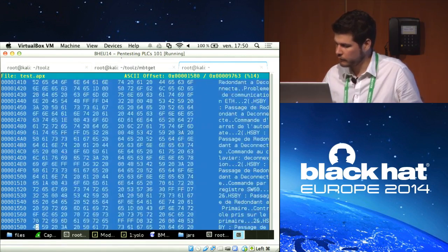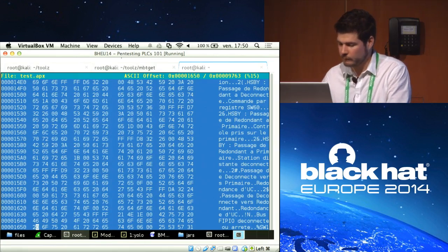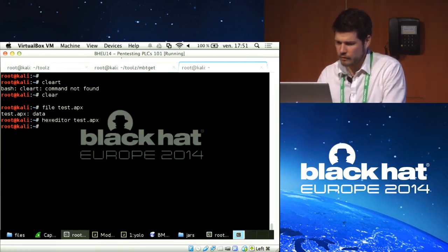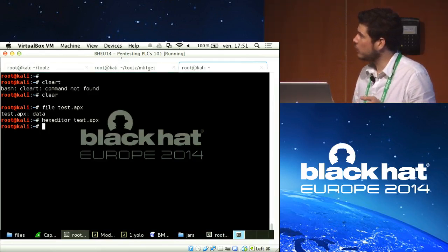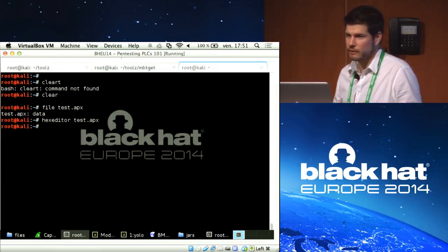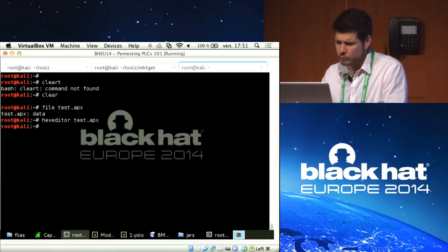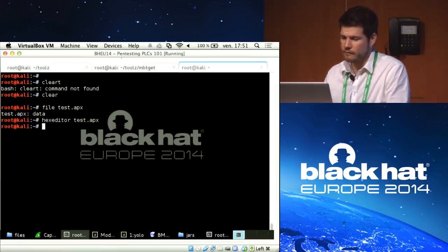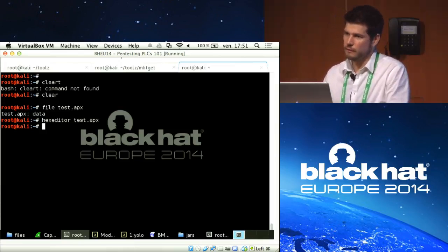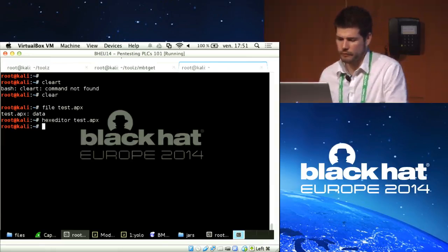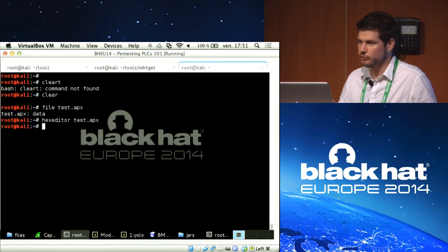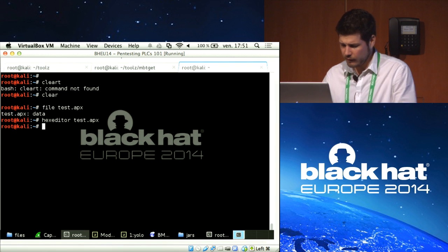So yes, here you can see that we recovered the program. The thing is, at the moment you do not know how to use it because the APX file will not be opened directly by Unity Pro. So what I did to be able to exploit it is create a dummy project in Unity Pro, archive it, and then it's a file with the STA extension. Then you just rename it to zip, you unzip it, and you can see what's inside.